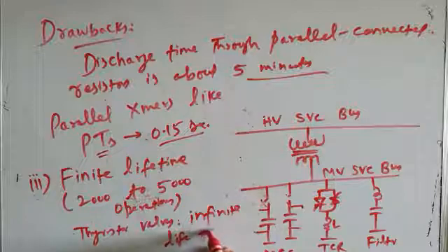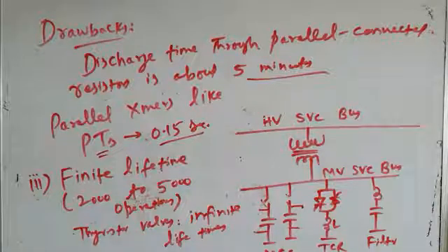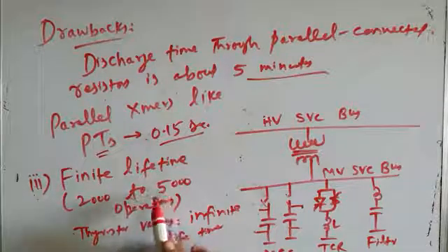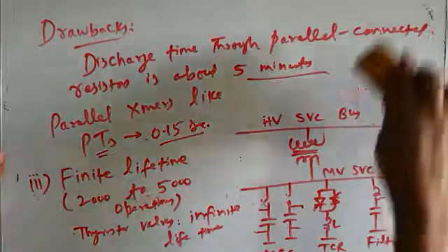So in TSC, TCR, SVC, we are using thyristor valves as switches, which have infinite lifetime. In MSC, TCR, SVC, we are using mechanical switches, and mechanical switches have a finite lifetime of about 2000 to 5000 operations.